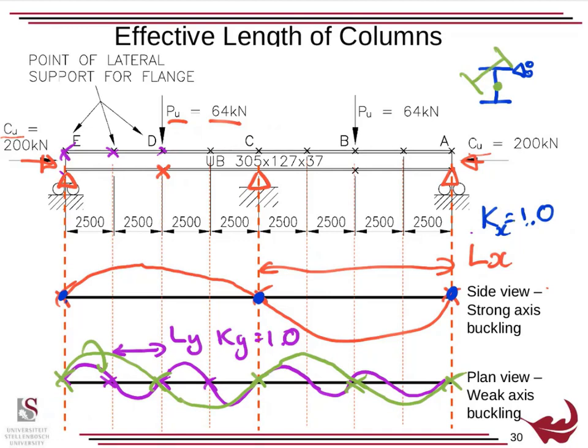So this is not 100% torsionally free here. If we test in this lab, depending on what is here, it might be some amount of restraint. I'm conservatively assuming that if the section can twist, there's no torsional restraint. But if this was a short squat column, we may actually find that just one point and the stiffness around it would be enough. But for sake of safe calculations, I've assumed that if there's only a single small point at which it's connected, it's not torsionally restrained. If there is more than one point, even if it's two little bolts, then it's torsionally restrained.